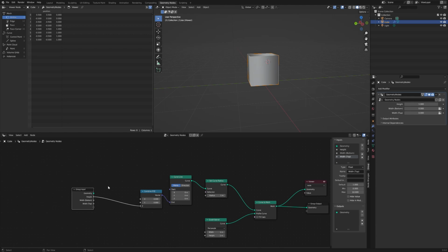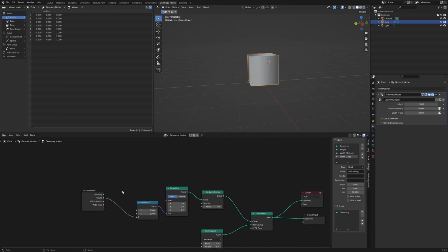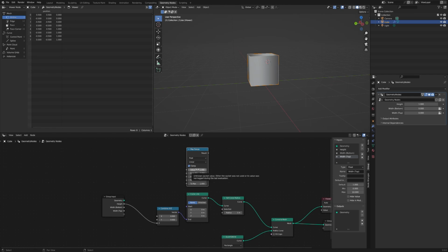And what we're going to do with that is we're going to map that as a range. So we want to interpolate between whatever the bottom is and the top. We just define the bottom and the top. Blender can work out the rest in the middle. And the way we can do that is with a map range node. And what that allows us to do is take in a value. And what this value is going to be is a property for our spline, our curve here.